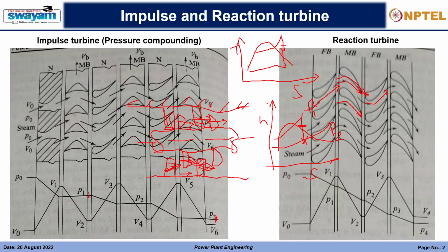So by utilizing the full potential, because we need to utilize the maximum amount of the steam, only then can we get the maximum area under this curve, and the maximum area under this curve represents the maximum work output or maximum efficiency. But we are limited by this particular temperature and this particular pressure. Why? Because in the condenser, although it is vacuum, we are cooling the whole steam with natural lake water, right?